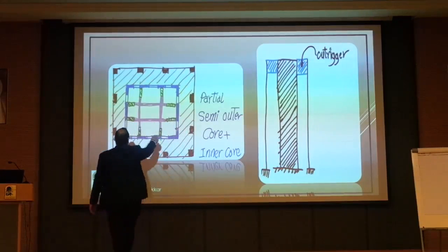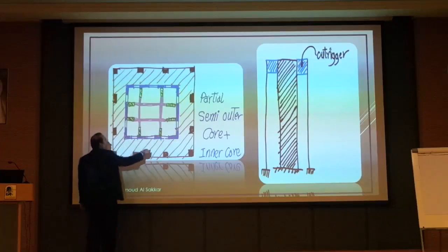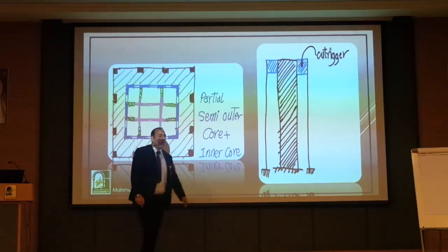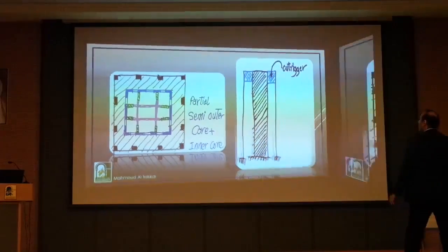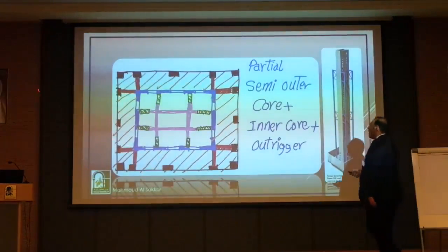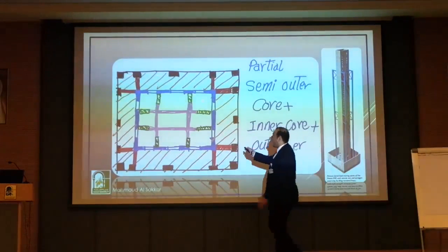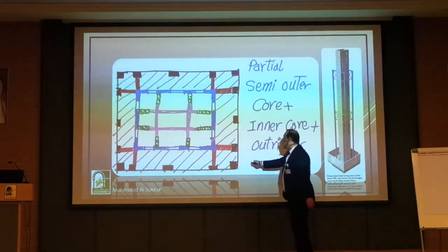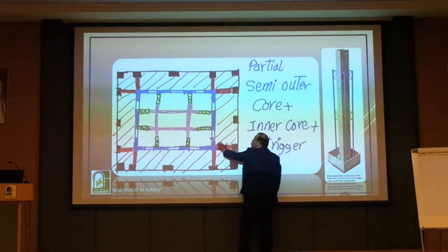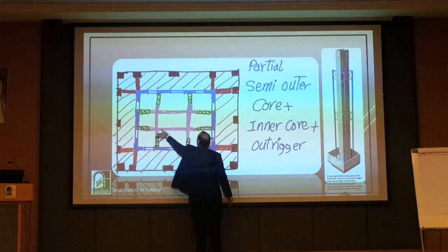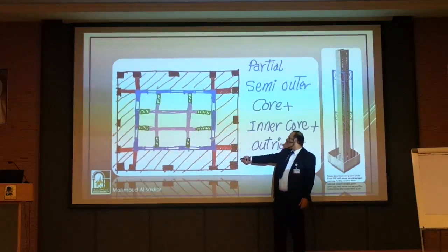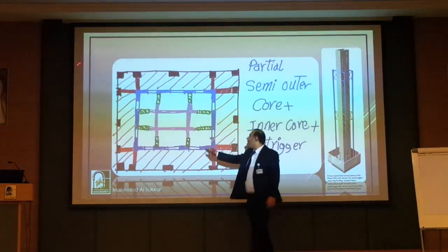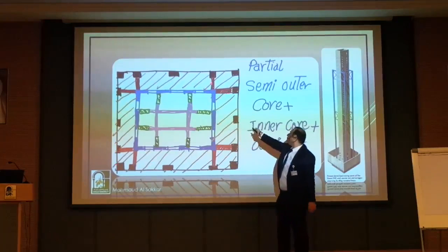What should we do here? We have our core, internal core. We have our column. Can we connect this internal core with our outer column, the outer hull? We have to make full use of this system. Can we? Yes. What have I done? I have just connected my internal big core with another column, an external column. Look, I have an outrigger here. One core for the whole building, but one outrigger only for 1 floor. Let's say if we have 100 floors, I have 50 floors right now. So connecting the core to 1 column, the adjacent column.